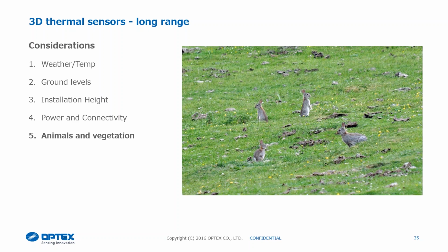And just to reiterate, Neil, the online training is free. It takes about 30 minutes of your time and is certificated as well. But it's imperative with the Red Bulls that you purchase the SIP-AT tool. Yep. So with that, you get the area viewfinder. That's just a little plate that you put in the front of the detector, and it'll actually show you, the engineer, the exact layout of where the detection patterns are. You can then plug in the walk tester and walk test it to make sure that the detection's falling in the areas that you want and you're not getting any of that overranging that we mentioned earlier on. So yeah, the walk testers are key.